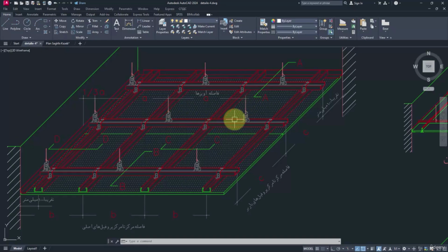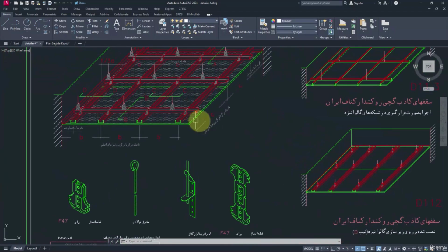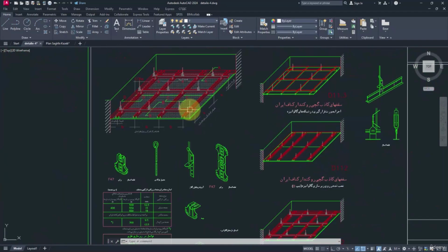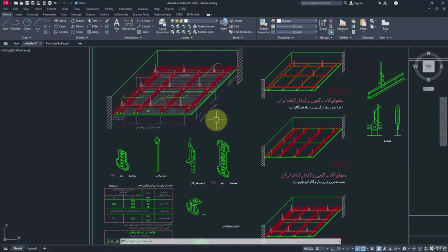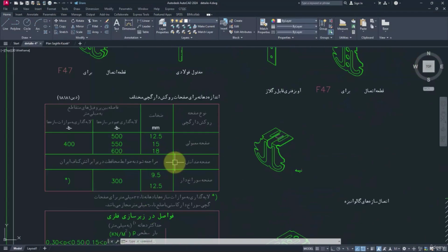Or sometimes, for instance, the dimensions of the ducts may change, so that we can remove or add more connections. So I don't recommend modeling these details for clash detection. But for a schedule table, yes, you can use them. Everything depends on your needs. Anyway, let us model it and get familiar with the way that we model them.